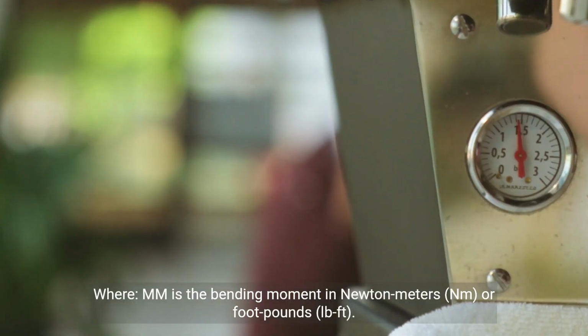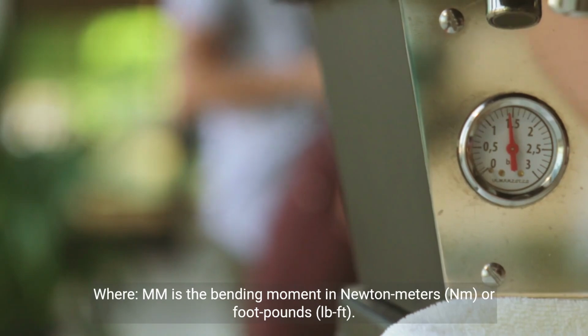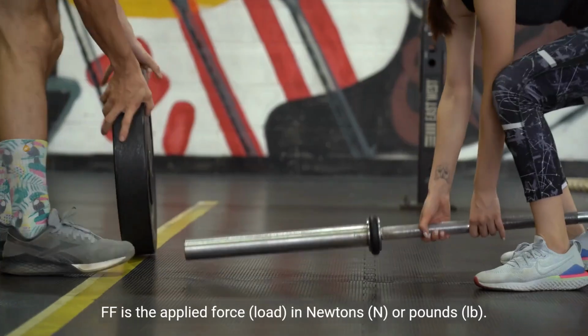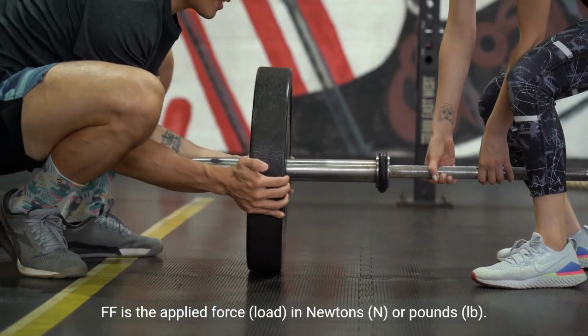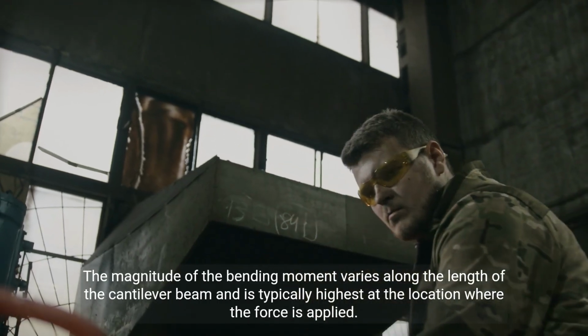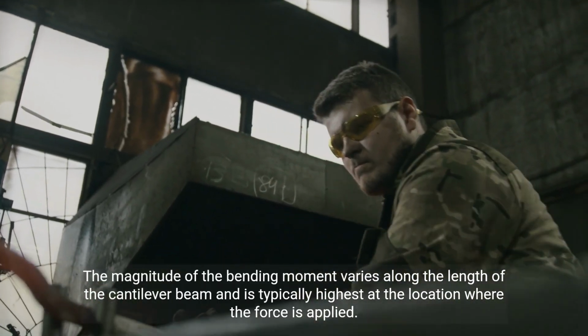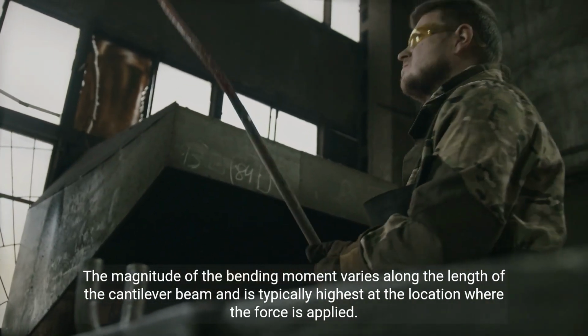Where M is the bending moment in newton meters, Nm, or foot-pounds, and F is the applied force, the load, in newtons, N, or pounds, lb. The magnitude of the bending moment varies along the length of the cantilever beam and is typically highest at the location where the force is applied.